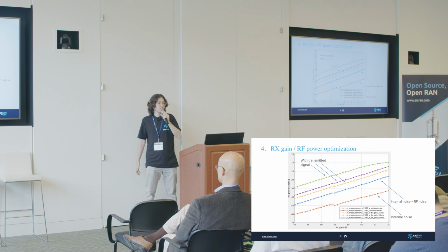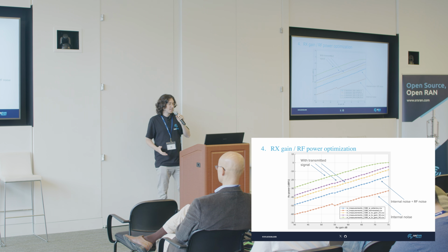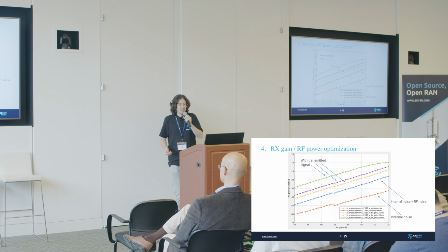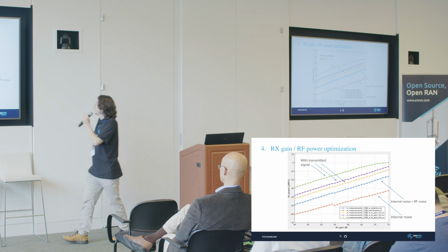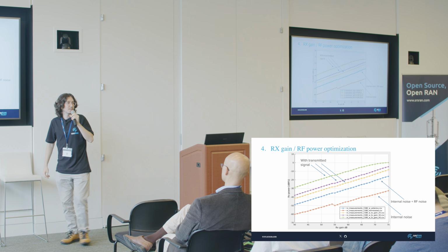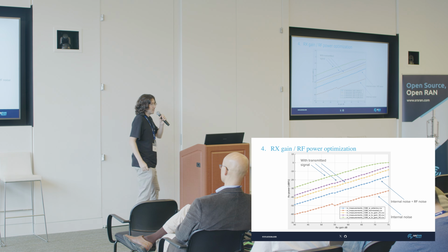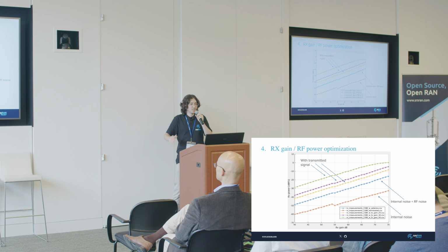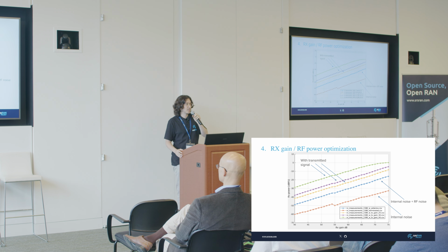And then the three remaining curves are the power that we measure when we also transmit a random signal at different transmission gain levels. It's noteworthy to mention that the green curve, as you see towards the top right, is showing saturation. The reason you see that is because it's approaching 0 dB FS of measured received power, which means that at this point, you are saturating the receiver.